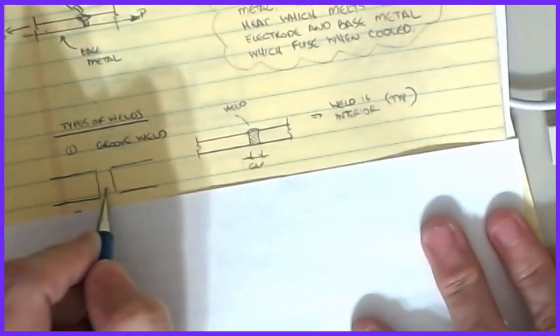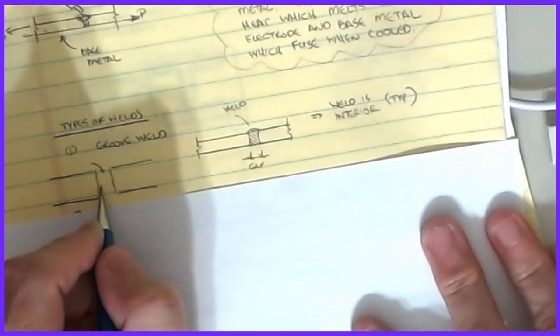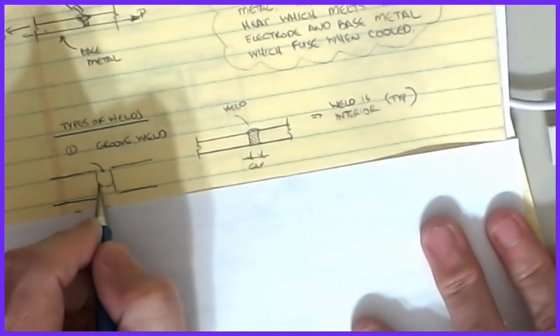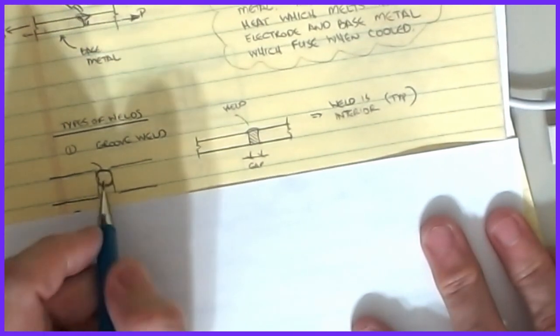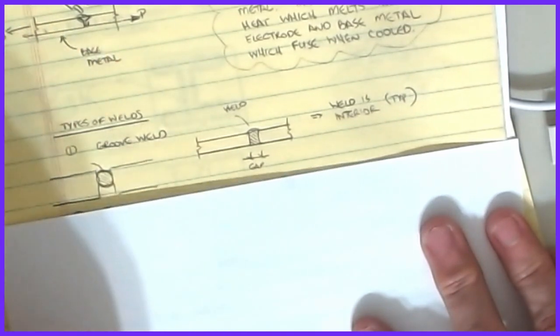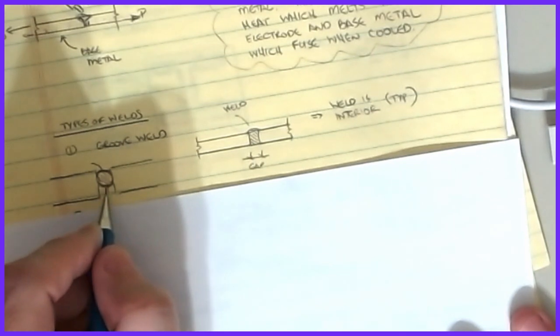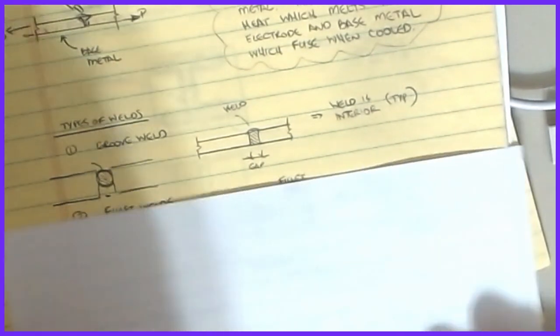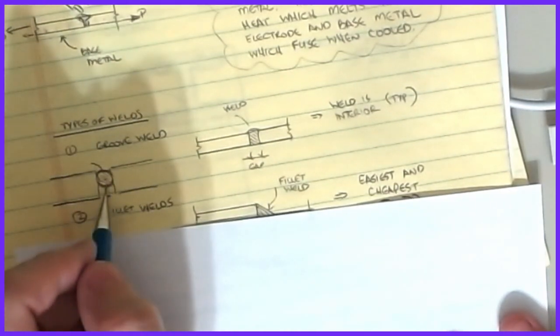Now, these have some issues and are the source of a lot of the minimum thickness requirements, because if this distance becomes too far and I try to fill it in, there's the potential possibility that this weld, as it's flowing into this area, cools and stops and never reaches the bottom. So we've got to have real good quality assurance of the weld that we're getting, because I'm counting on this entire area to transmit through here, but if I get shortchanged on this and have some sort of gap there, then that's a significant reduction in this.